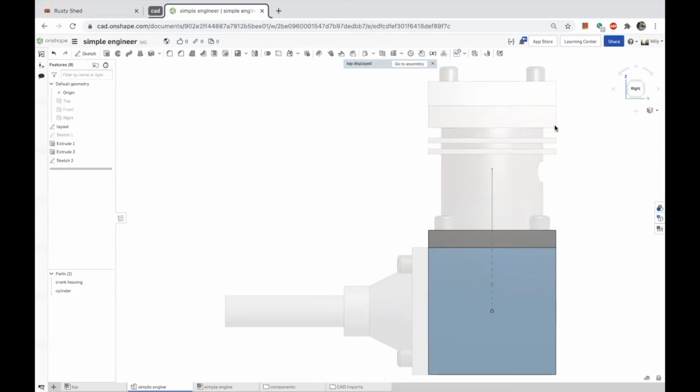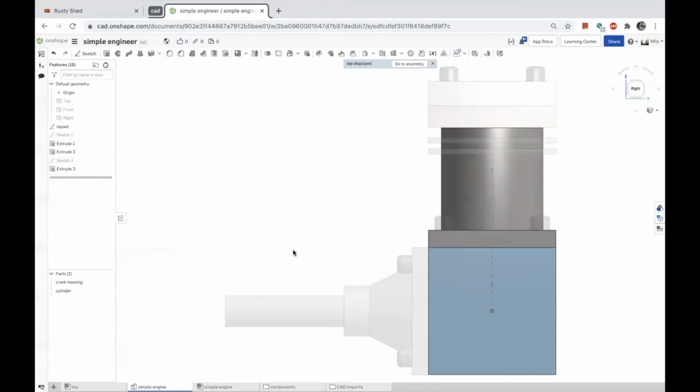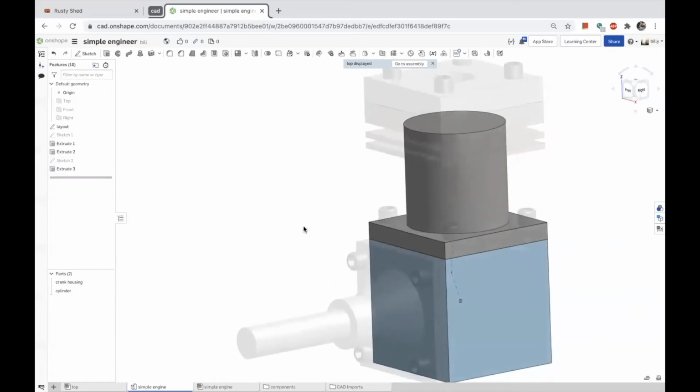Escape. Yeah, this is probably designed in inches and I'm working in millimeters. It'd probably be better if I switched to inches, but you know what? I'll just keep copying these. So let's go, we'll extrude this up. And I want to add it, and it automatically figures out how high up. I paste it from my measured value, okay? Let's go ahead, we'll create this.